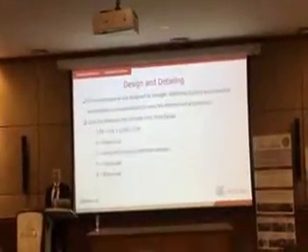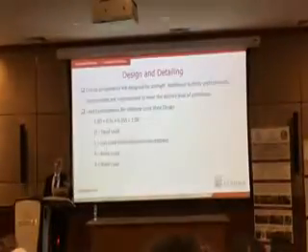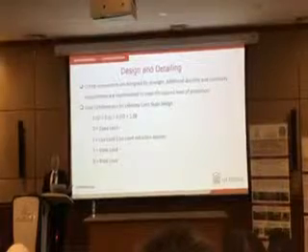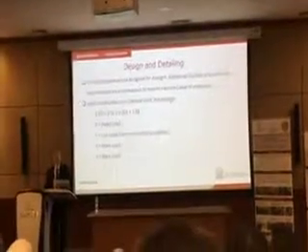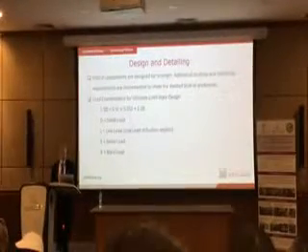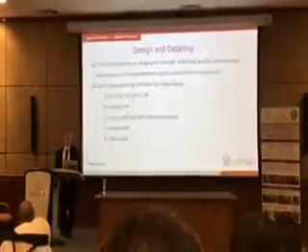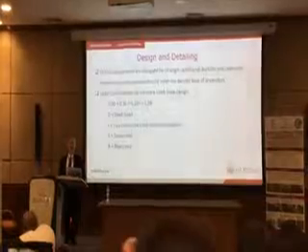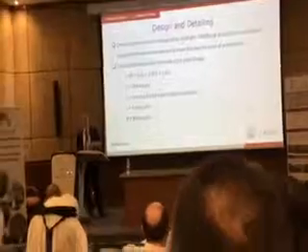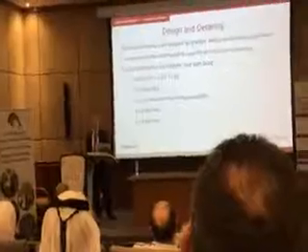So once you meet these performance levels from the analysis side, now the last step in completing the design is to do structural design and detailing. And the load combinations used are dead load plus half of live load. In Canada, we have snow load, a quarter of snow load. Blast load is not increased because it's a rare event, just like in seismic events, we don't increase earthquake loads. The increase is already built in, or the risk associated with